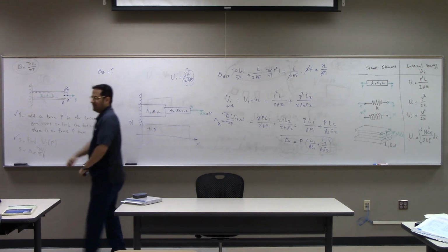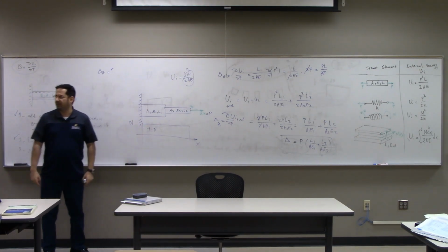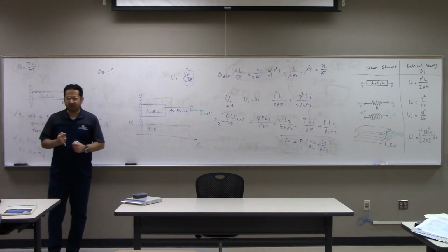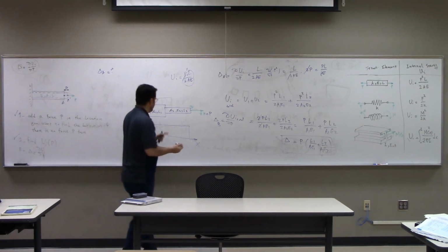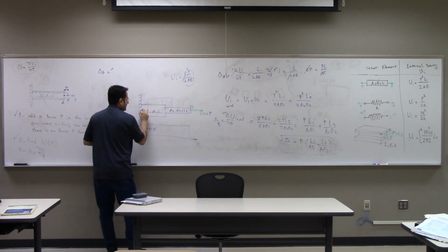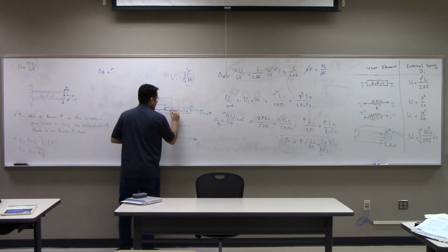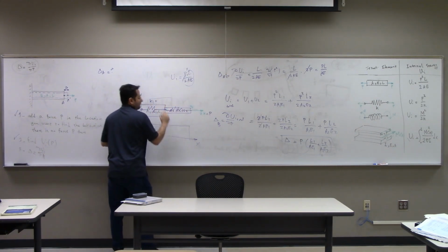Another thing is, if I want to solve this without using the energy method, Castigliano, what's the next easiest method that I can use? We already discussed it before. Find the K for each one, or the method of combining springs. That we've already discussed. So that means that if you replace this guy with a spring, and this guy with a spring, what's the spring constant for this? K1.